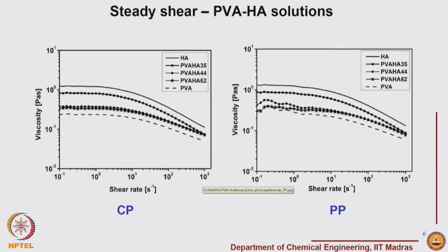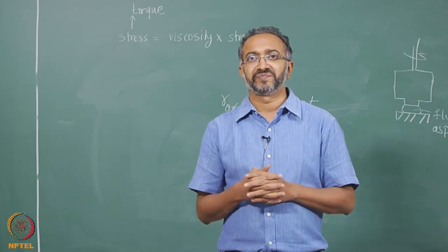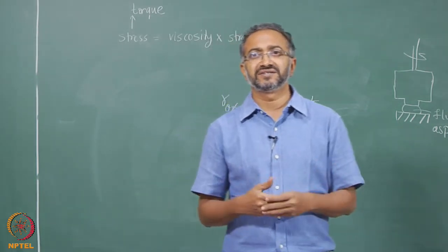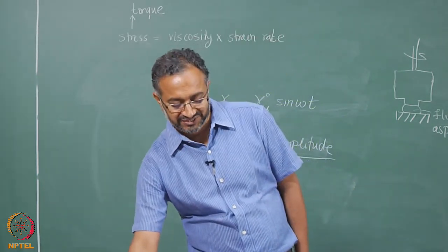So what one has to do is to do more systematic experiments. You can maybe measure at, let's say, strain rate of 0.3 as a function of time to see how reliable and repeatable these results are. That's one way of doing it. You can also sometimes do some systematic analysis of composition itself. So in this range, if you change the composition and if you get a systematic result, then you can explain it based on the mechanisms which are related to composition, then again you can say the reliability is better. Therefore, most of these kinds of measurements, when we are trying to do them for new materials, we really don't have any guidelines from earlier.